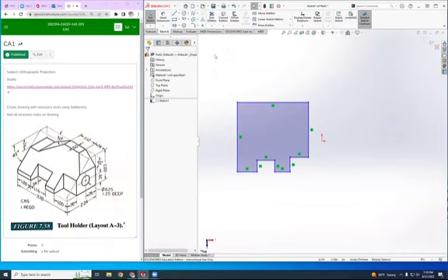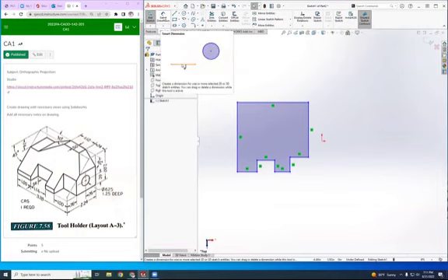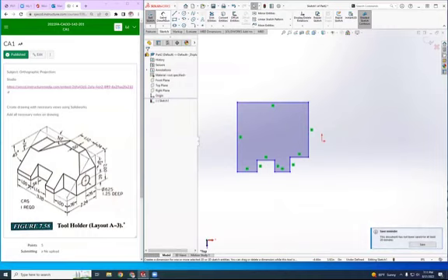We need to add geometric constraints, which are these right here, like vertical, horizontal. All of these are geometric constraints. Coincident constraints, right? Those are all geometric. Now, on top of that, after you do the geometric constraints, you want to add dimensional constraints. And this is what's going to make it more accurate.